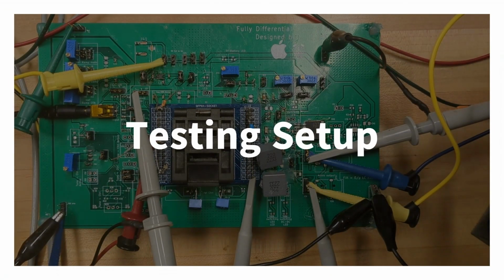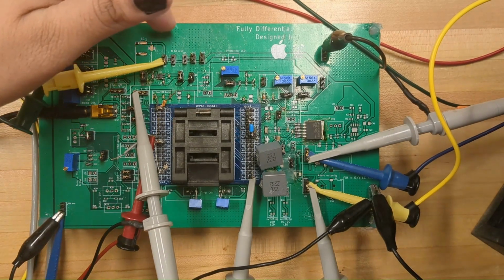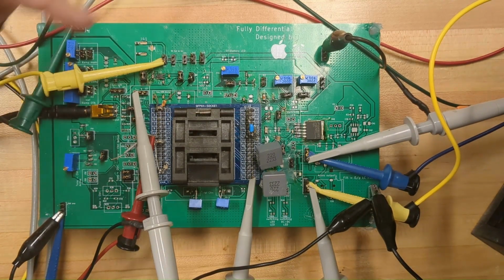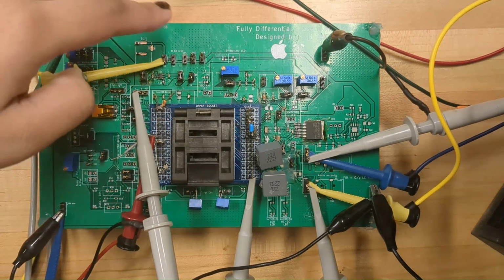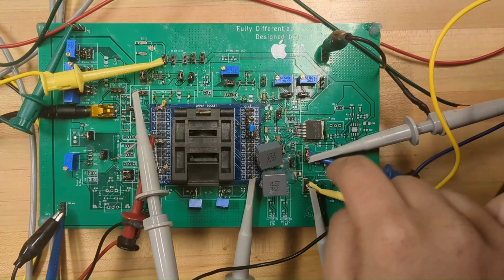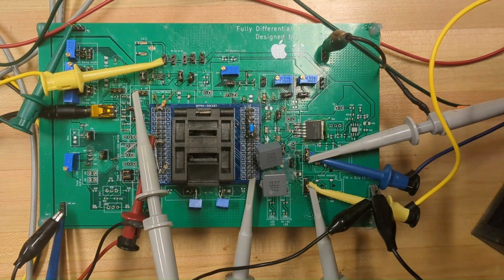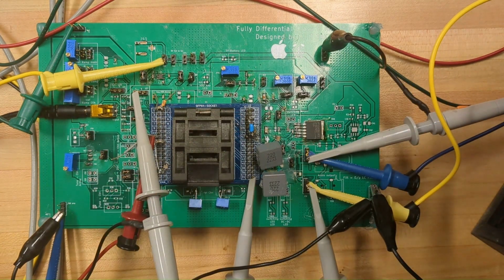So let's go over our testing setup. We are feeding a 5 volt external supply which comes in over here, and we have two LDOs on our PCB. We have one LDO over here which is the analog side LDO, and the other LDO is over here which is the switching side LDO. The idea behind dividing the power domain into two parts was to avoid getting any noise from the switching side to the analog side.